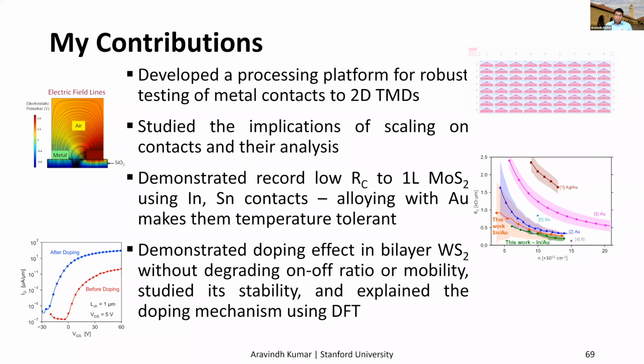For the underlying layer, I would say indium and tin are good choices. We can try bismuth. But if you want to go for P-type contacts, there you need high work function, then you start running into toxic chemicals like tellurium and selenium, but they are really high work function. They have low melting points, so they are good candidates, provided we can work with them in a safe environment.